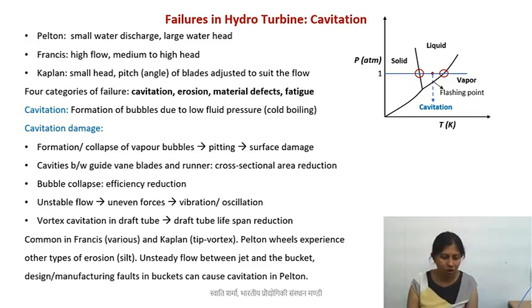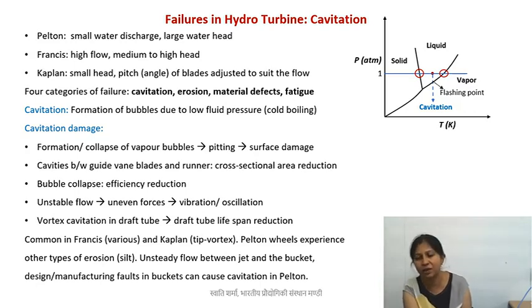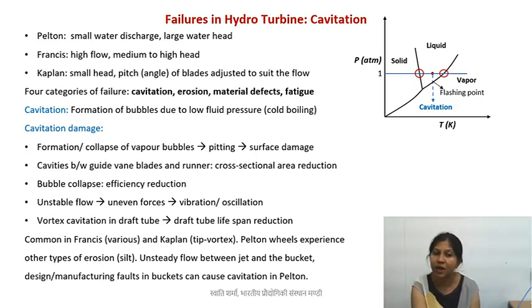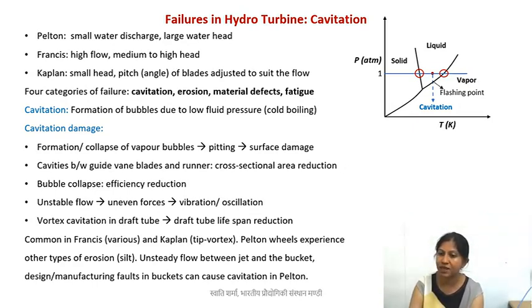Okay, so what do you think? Do you have this kind of cavitation also in Pelton wheels? Generally Pelton wheels you will operate at atmospheric pressure, but Francis and Kaplan will definitely have a higher probability of having these bubble vortexes inside the draft tubes, inside the casing.